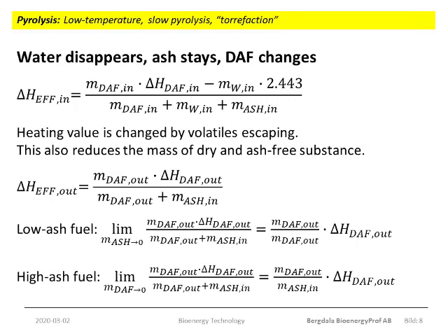Pyrolysis is a conversion process with many phases. There is flash pyrolysis, high temperature pyrolysis, pressurized pyrolysis, and a lot of other process variations depending on what you're after. But right now we limit ourselves to a slow and low temperature, typically some 200 to 300 degrees Celsius, atmospheric pressure process. And this process is called torrefaction. What happens in this process is of course that the material is dried. So the water disappears. The temperature is so low that none, or at least only a negligible part, of the ash is gasified and disappears.